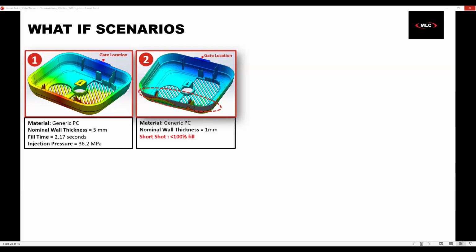So let's take a look at the second. Let's say we decided to split the difference. We discussed that instead of changing the one model, regenerating, and running it, you can make a new configuration. Yep, I made a new configuration. Those are just regular SolidWorks configurations, and then I duplicated the studies so I didn't have to set them up again. Although all the work is in the first study, after that we should be able to leverage a lot of our work.